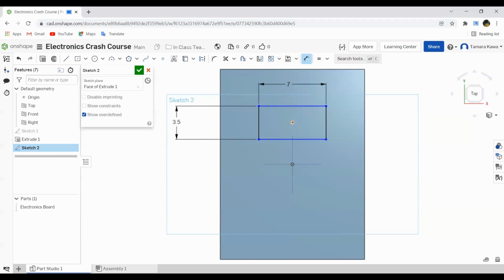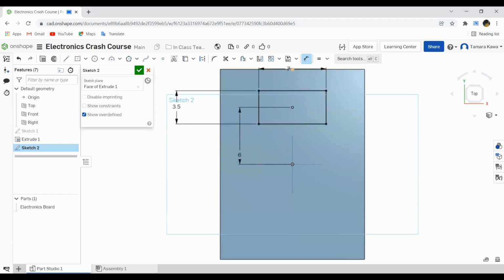And there you go. You'll also need to define its length from the origin because, again, we're vertical with the origin, but we can still move up and down. So we'll define it as, let's call it 6 inches from the origin. And let's actually make that a little bit bigger than 7. Let's actually make that 7.5.